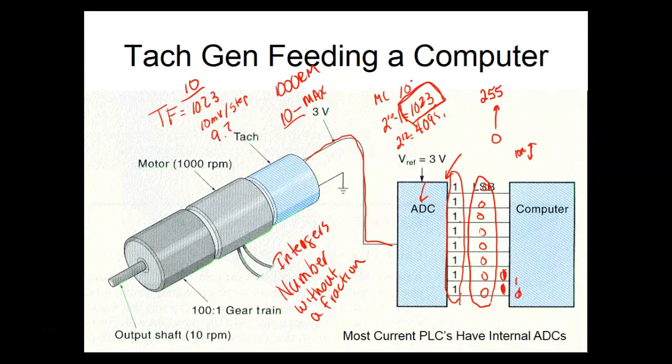So these guys on these A to D converters, they only switch at certain spots. And they're not rounded either, guys. It has to exceed the step. So that means these guys cannot switch at 9.7 milli. They'd have to switch at 10. And then when it got up to 1023, it means we were putting 10 volts in.